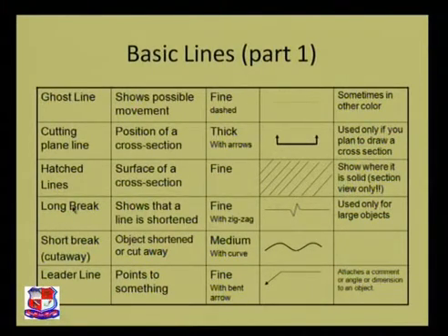Another would be the long break line. It shows that a line is shortened. It is a fine line with a zigzag. I am giving you an example in a bit. Another one would be the short break line. It's again an object shortened or cut away. Medium with the curves. Long break line or short break line are all equal to the same.